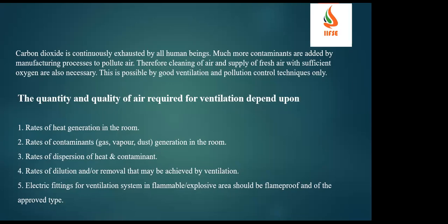There, we should ensure that we are giving a proper oxygen supply. Or taking an industrial example, if you are entering a confined space, we put in an exhaust or a ventilation hood, or sometimes we give a breathing airline to the entrant who is entering the confined space.